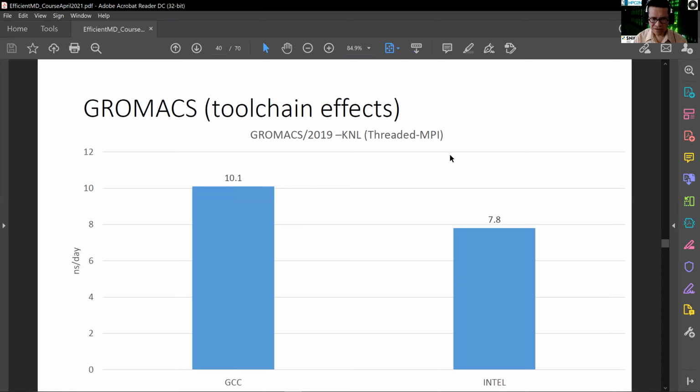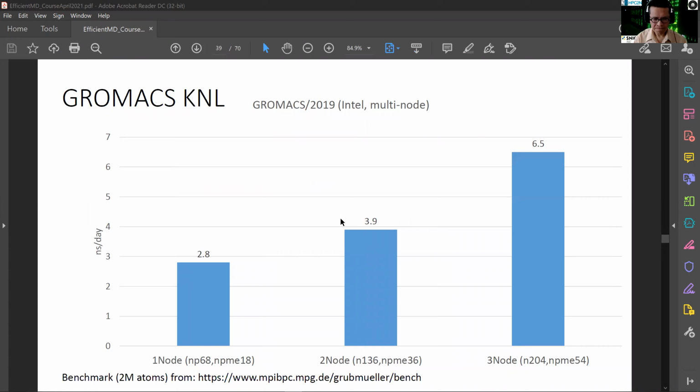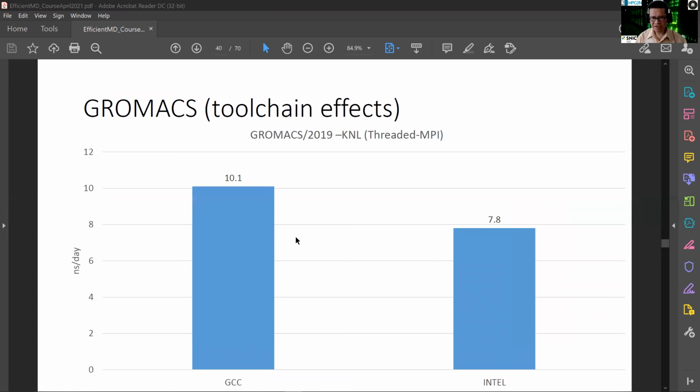So there is a question: does the 2 million atom system need PME? Well, I remember that in this case I ran the PME tool, and it shows this number here. And also I tried different combinations of the PME, and the ones that I presented were the most efficient ones. And this is a good question, because depending on your system, the combinations of PME and also OpenMPs and MPIs could make your simulation more efficient or less efficient.